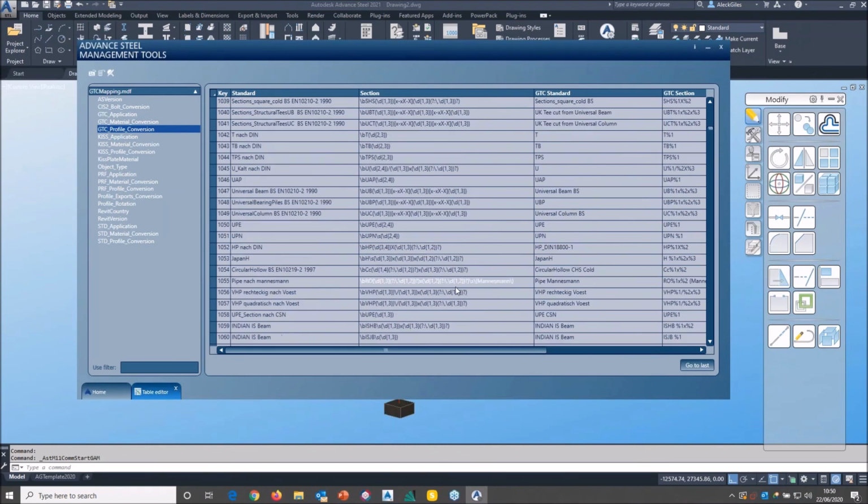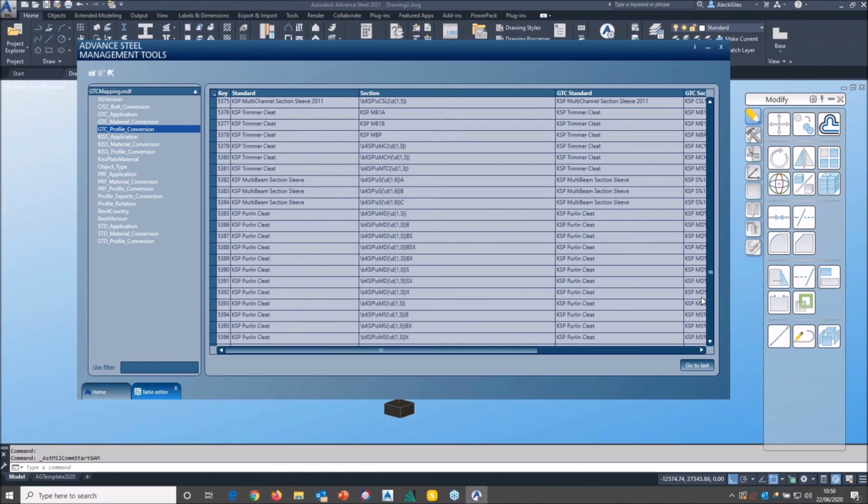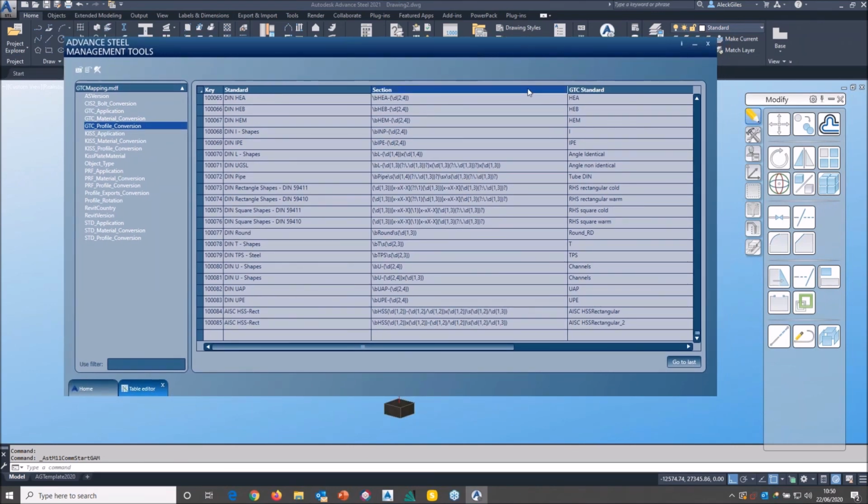So to find the right line that you've just mapped is quite challenging, but if you can find the right line, yes, you can delete it from there. But be warned, obviously, if you delete the wrong line, then you've lost the mapping of something else. So you want to be really careful because you think the ones I just did would be at the bottom, but no, they're not. So I would say at your own risk. I would always keep a backup before I ever touch anything in the database and ever edit anything. I always back up the database first. So if I don't like the result, I can put the original version back.